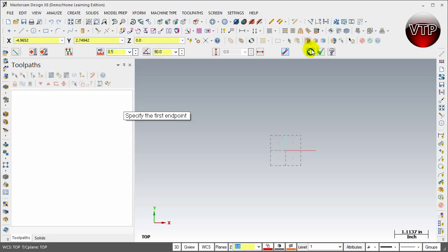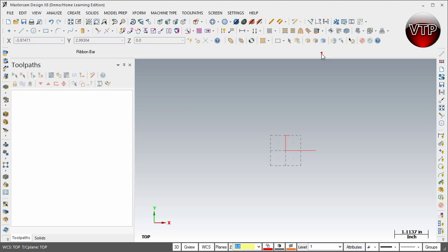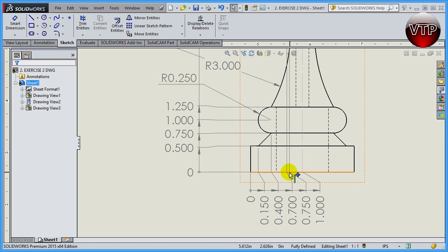There you go. Apply to accept it. Again, left click. And this one's going to be 0.15. And then click on OK to accept that. And then OK to exit this. Now all we've done so far is create this: 1 line, 2, and 3.